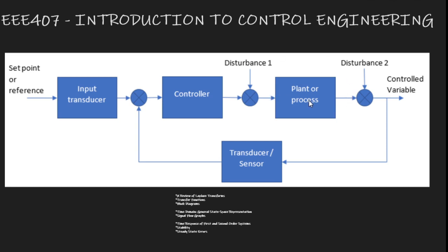On the other hand, let's assume we don't have the Laplace transform of the output, but we have the transfer function of this plant or process. Like we said, for instance, the transfer function of an amplifier might be 2. If that is the case, then whatever the input is here, input multiplied by my transfer function tells me what the output will be. Now that is very useful.